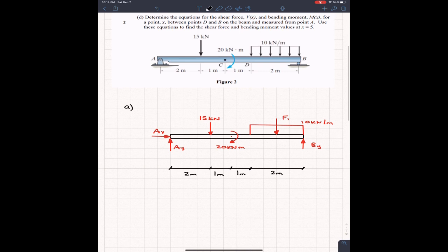So now this is one of the things I get asked. For this free body diagram, it's good to go. It has all my external forces. It has all my reaction forces. And to finish it off, it has the dimensions of the beam.